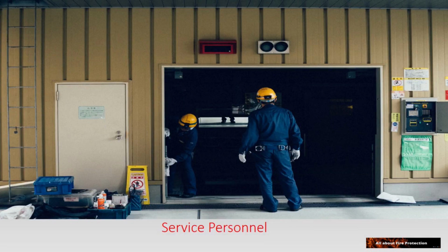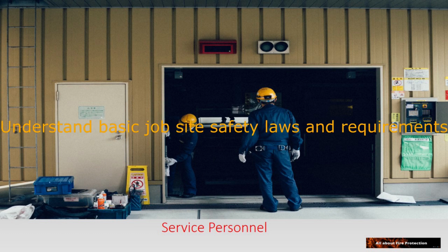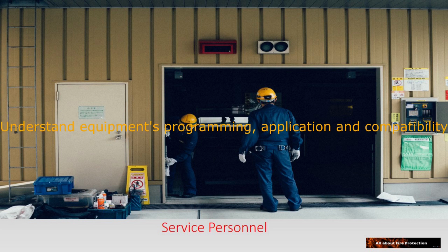Service personnel shall be qualified and experienced. First, understand the requirements contained in NFPA 72. Second, understand basic job site safety laws and requirements. Third, apply troubleshooting techniques and determine the cause of alarm system troubleshooting conditions. Fourth, understand equipment-specific requirements such as programming, application, and compatibility.